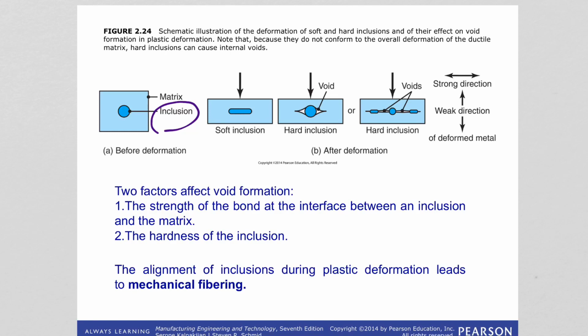Okay. And the extent of their influence will depend on factors such as their shape, hardness, distribution, and the greater the amount of the inclusions, of course, the lower the ductility will be. And during manufacturing, because of these inclusions, voids and porosities can form in the metals. So two things are very important.